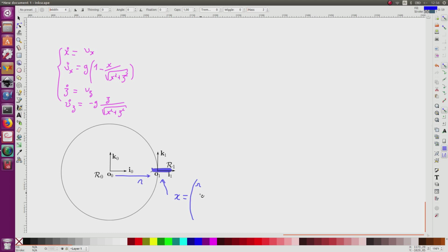Then the speed corresponds to 0, since I know it is fixed, approximately fixed. Here it will be 0 and 0, so I have to linearize around this state vector, and I will get something like x dot equal a matrix A which depends on x, which corresponds to the Jacobian matrix, multiplied by x minus x bar.